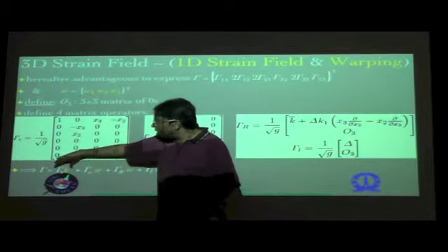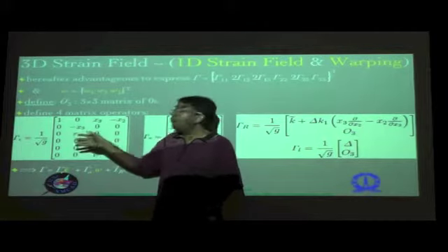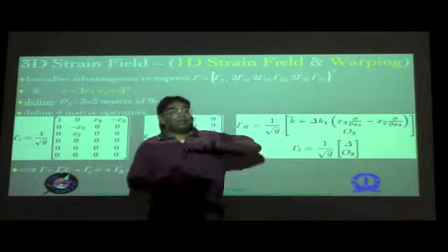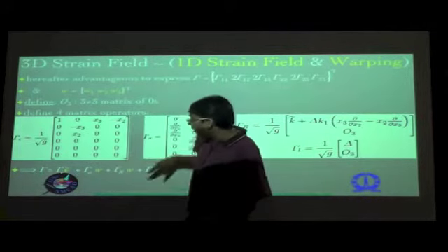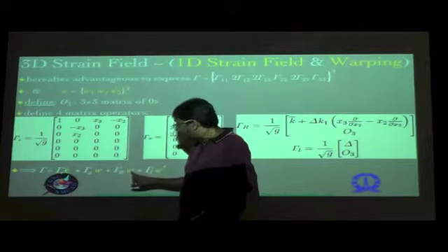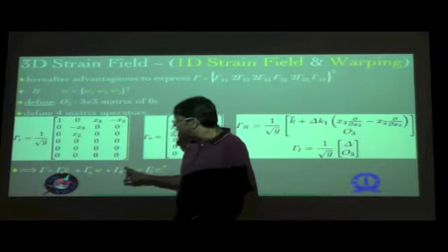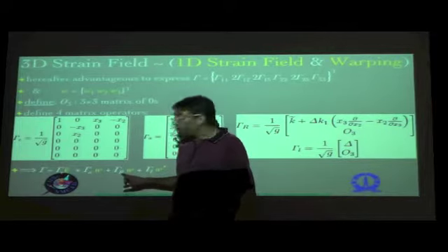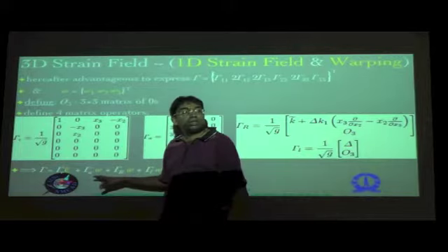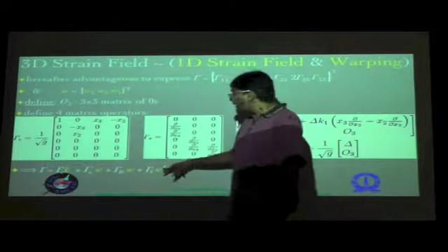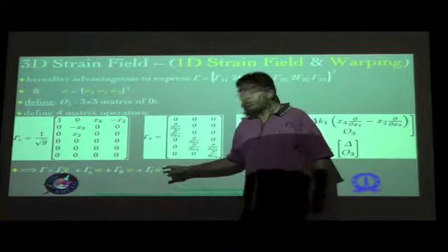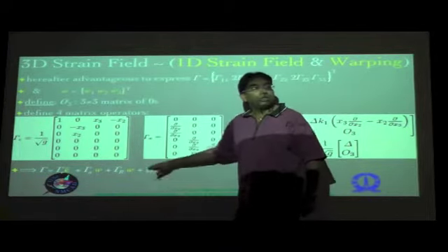So this particular term takes care of all the contributions which are coming from the 1D strains directly. The rest three terms that you have over here are all W dependent terms. This is W itself, this is again W, but the difference between them is this is due to initial twist and curvature, and this would be present even without the presence of initial twist and curvature. And then finally W's which have derivatives with respect to x1, and therefore its contribution is what is included in this.